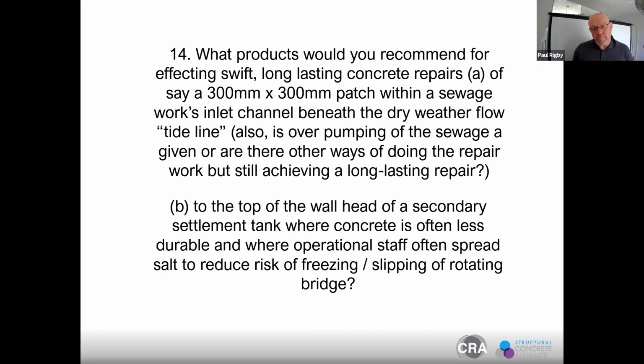I was going to say the question might be leading us to think about the compatibility and the cure time. If there is time for full curing before a resin-based lining or GRP lining is applied, which will be bonded, then traditional cementitious would work.